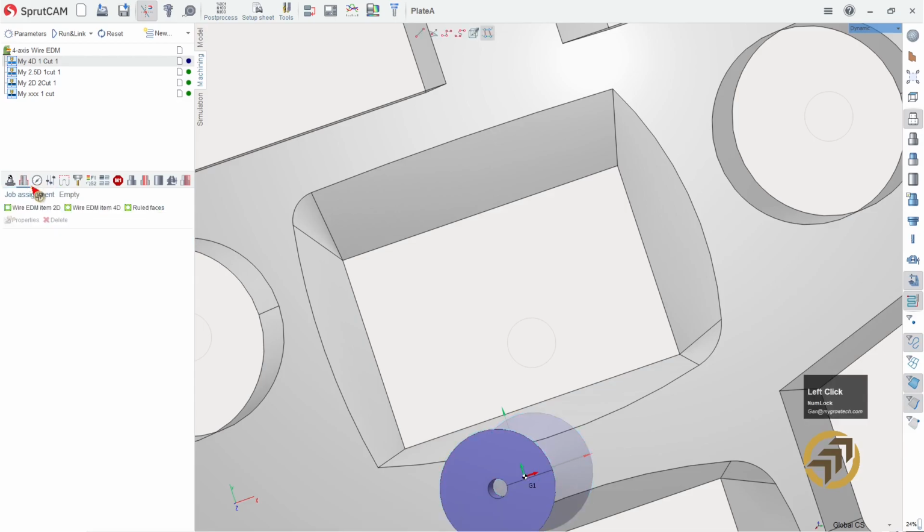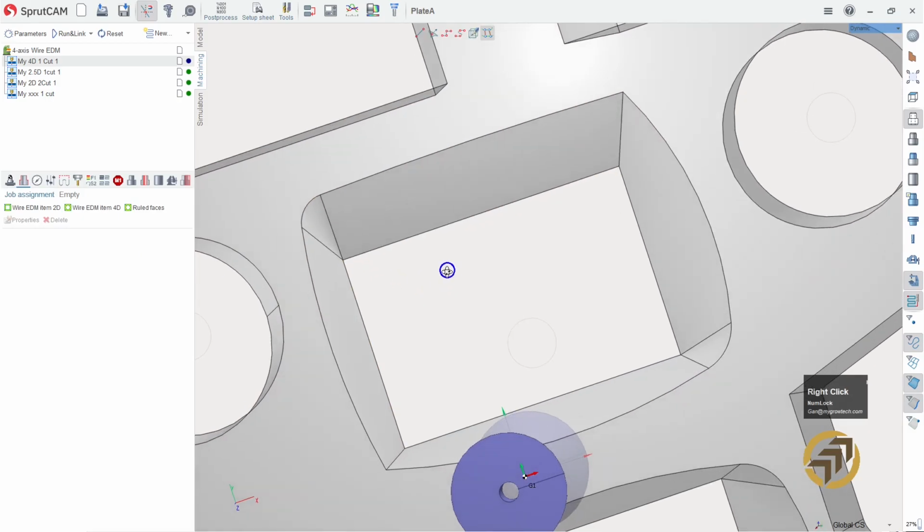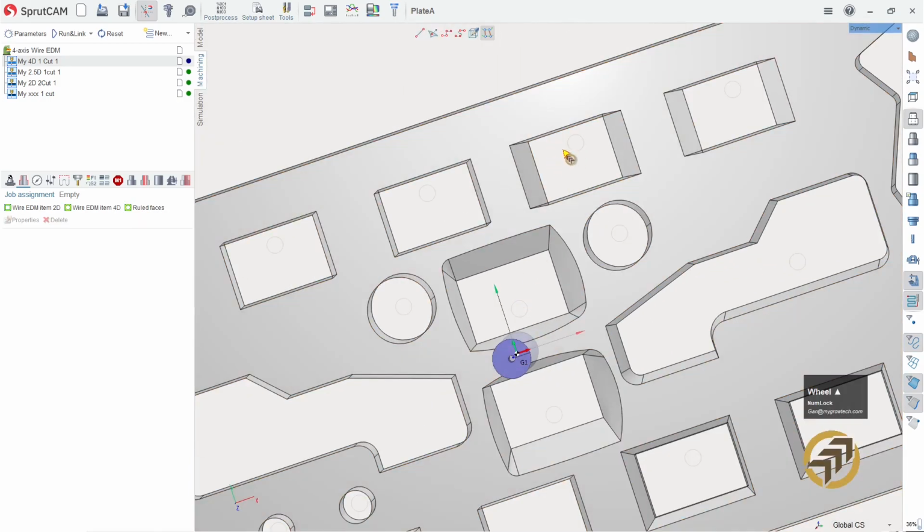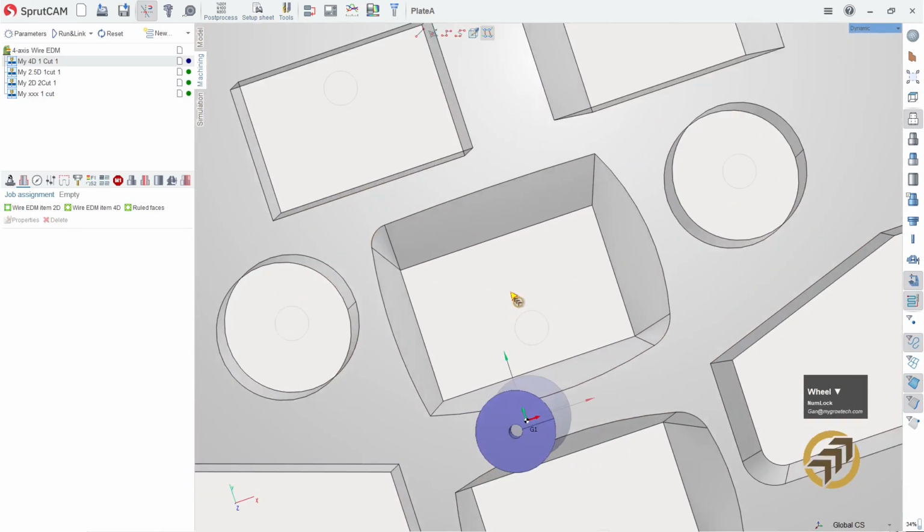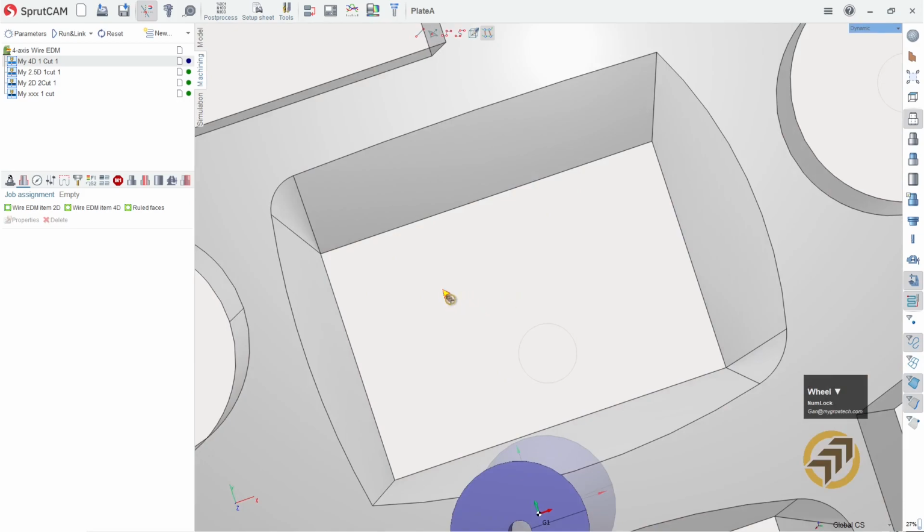And then go to select a geometry. Because the lower edge amount and the upper edge amount are not the same, we cannot use a surface, as what we have done with this lifter pocket. So we have to use the contour. The first contour that you should select is the bottom one, then the top one.